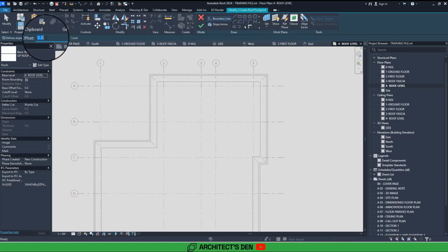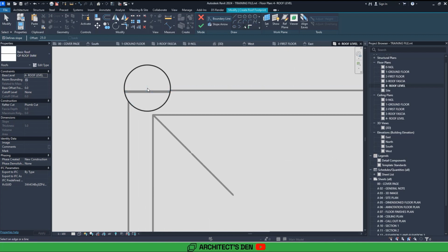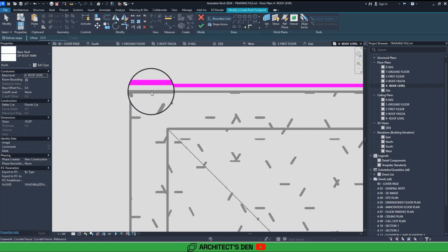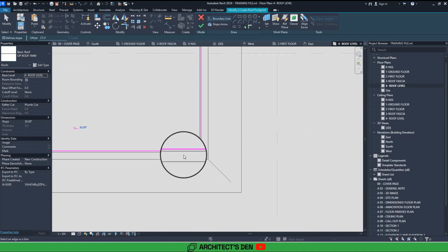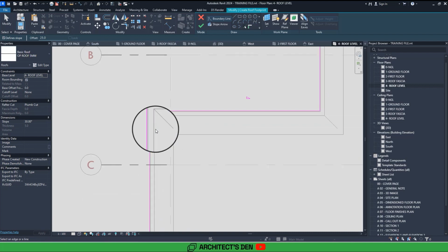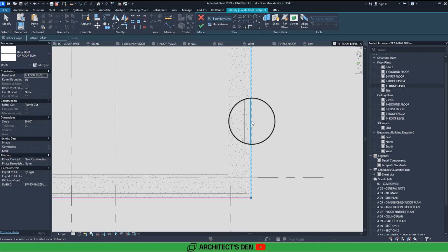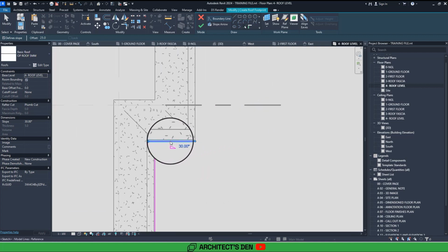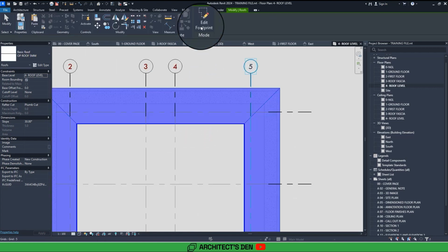I'm going to select an offset. The roofing sheet always covers the concrete fascia. Let's say 50 mm, 25 mm. So I'm just going to set an offset of 25 mm over these edges I'm picking. I'm just going to scroll down, zoom in here, click on this. You can see that slight offset of the roof over that space. If you use Tab to select it, as long as it's a continuous line, it's going to select everything at the same time. But I'm just running this right away.